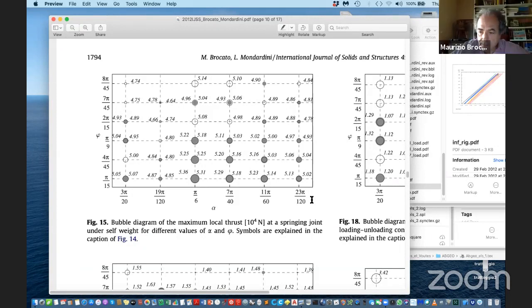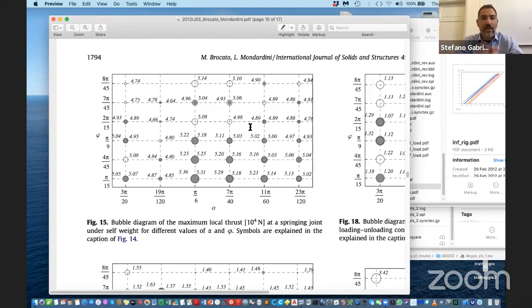Very interesting. I didn't know anything about this kind of flat vaults before. I was thinking about the behavior of an arch, in which you have the bending effect with respect to the thrust. It also is dependent on the span to height ratio. Is there in this kind of structures a geometric ratio that regulates the effect of the bending stiffness with respect to the axial or membrane stiffness? If you see it in the large of the 2D structure, that regulates the behavior of the structure, that is from a vault to a plate or something like this. I don't know if the question is clear.